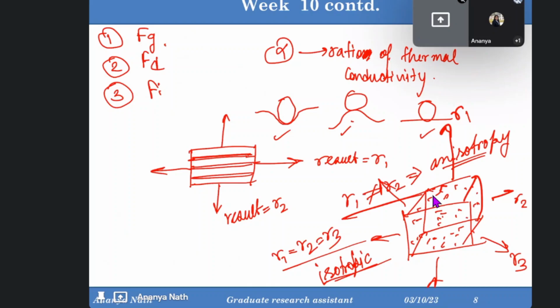Then there is the rule of mixture. Depending on the volume fraction that you take of the reinforcement particle and the matrix, you will calculate the elastic modulus of these two types of materials, and then you add, subtract and multiply with different terms to get the stress value.